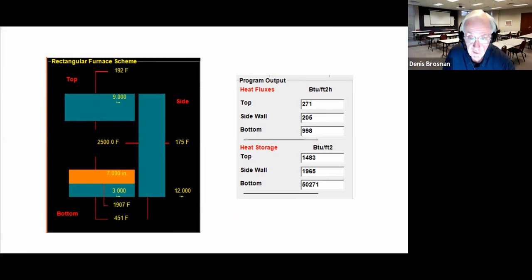Well, that is the advantage of fiber linings. If they're mechanically durable in your furnace environment, they save a lot of money in heat storage as well as heat loss in a furnace wall. Particularly, you're going to notice that in an intermittent kiln because of the heat storage that occurs on each heating cycle.